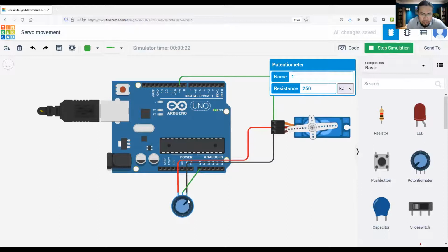So you see that the potentiometer has graduation of levels, or it has values. And then if you increase the potentiometer value, you could see that the servo motor is increasing its angular rotation. We know about motors as a device that generates rotational motion. So this potentiometer, increasing or decreasing that value, actually a potentiometer is a voltage divider.